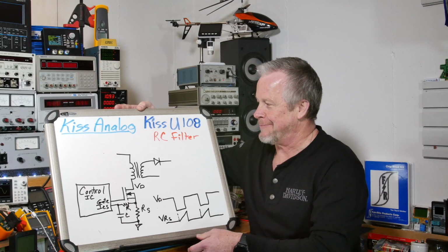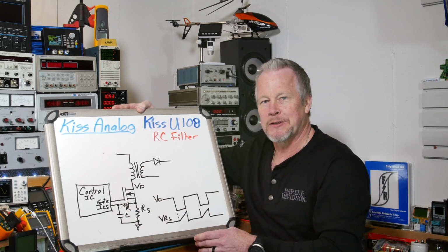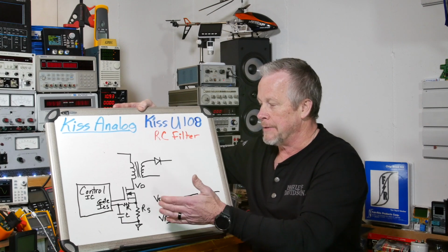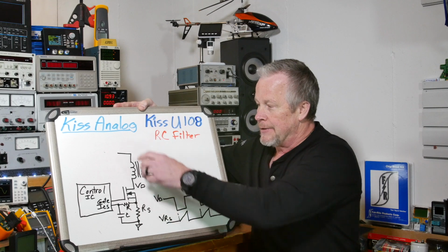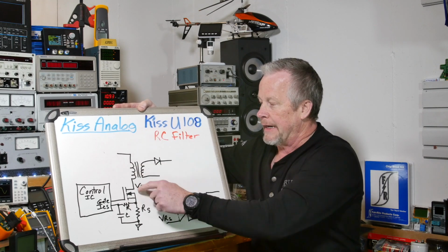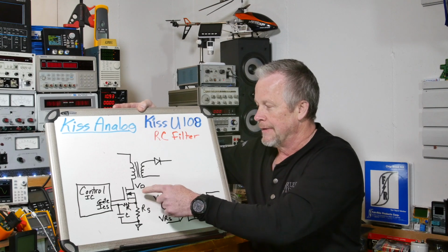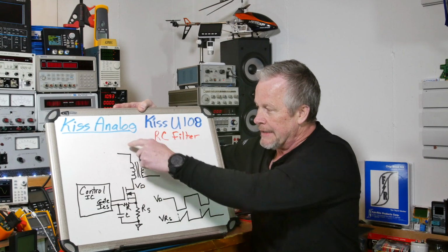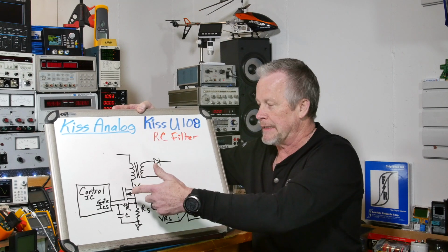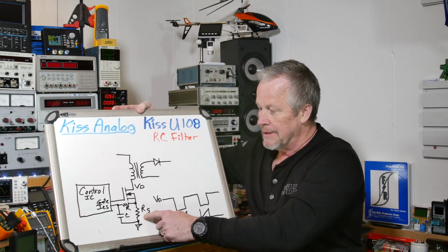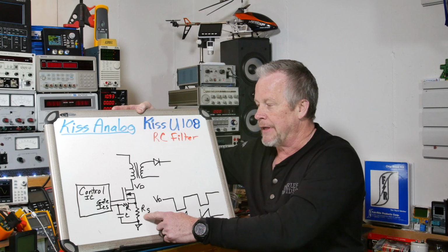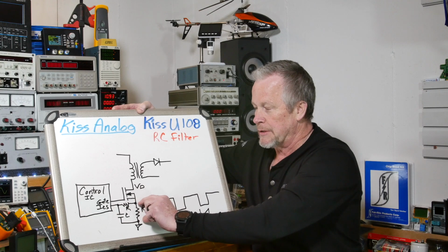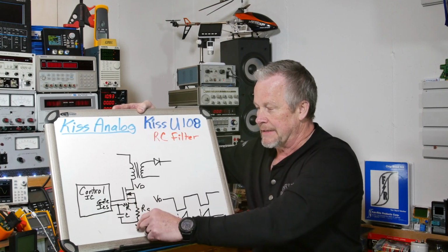Alright, I'm back with my example. I've got a portion of a power supply drawn up. This could be a forward converter, for instance. Or, you've seen a lot of the converters where there's a magnetic inductor transformer tied to a MOSFET that's switching on and off. And this is the voltage of the drain. When this guy turns on, he's pulling current through this inductor transformer, and then it goes to this sense resistor. Usually a small value, so you're not burning any power, plus you don't want too much voltage drop here at the gate to source of this guy, right?